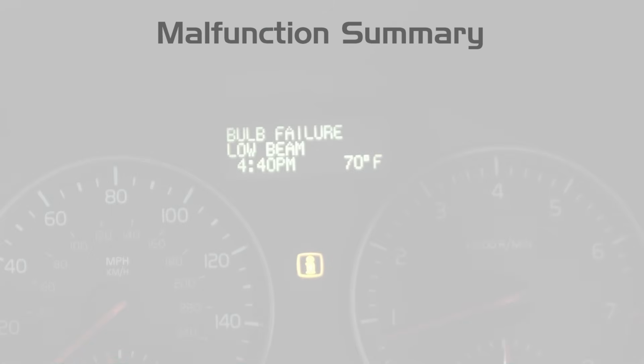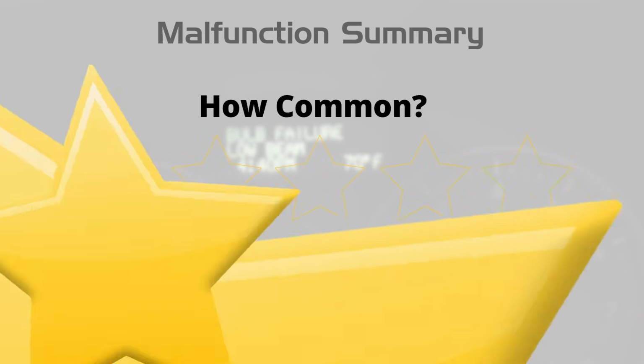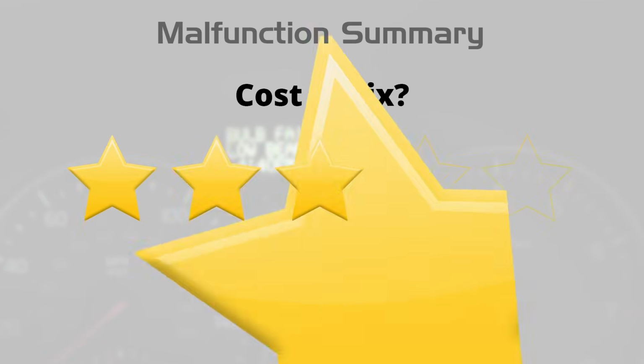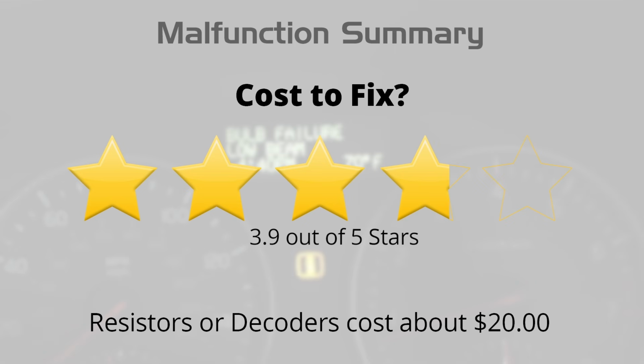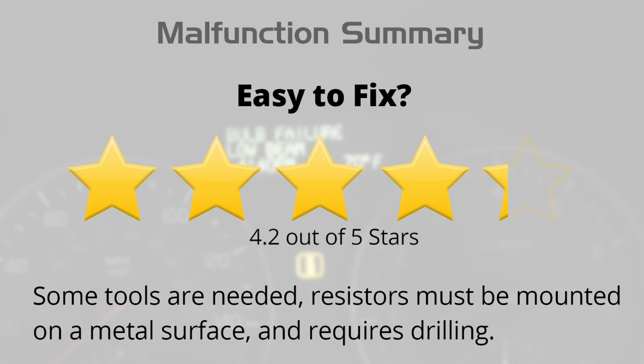Malfunction summary. How common is this issue? 2.4 out of 5 stars. It's only common on European vehicles and some American vehicles. How expensive is it to fix? 3.9 out of 5 stars. Resistors or decoders are available for around $20 on the market. How easy is it to fix? 4.2 out of 5 stars. Resistors must be mounted on a metal surface and requires drilling.